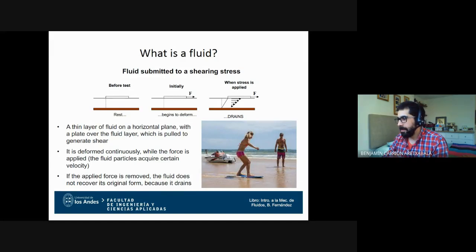The first concept that is key to this idea is the no slip condition. The second one is that we're talking here about forces, but actually in the analysis, we're talking about shear stresses. A shear is a stress, a force that is tangential to a surface. If we go back to the cats being fluids, if you pet a cat and slide your hand over it, then you're inducing a shear.